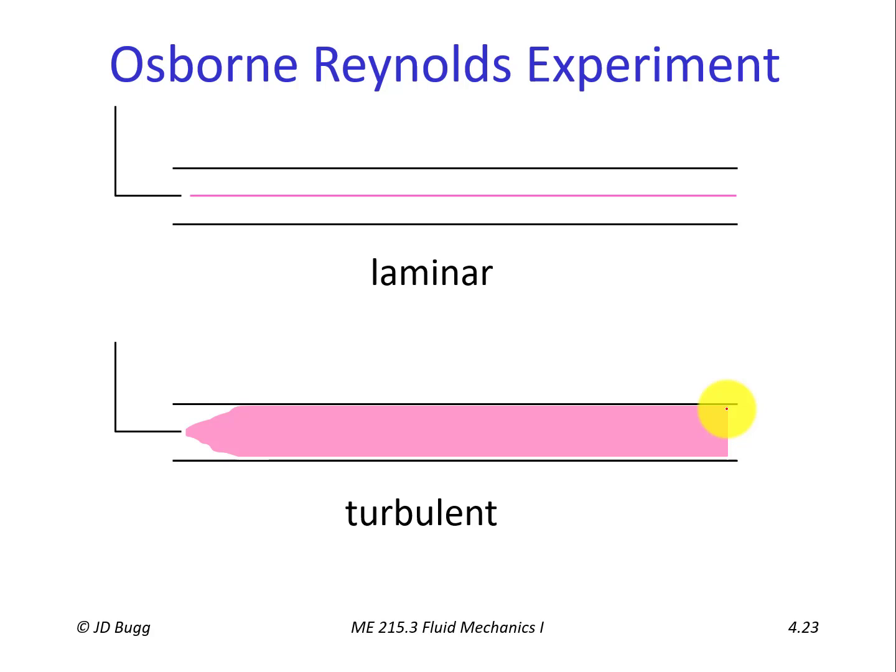So one of the fundamental things that we need to understand as we analyze pipe flows is the difference between laminar and turbulent flow. Because it turns out that the way we calculate that friction factor is different for laminar and turbulent flow. Eventually we'll see the equations that we use, but there's a different equation for laminar and turbulent flow. Now, before we worry about the equations to calculate friction factor, we need to continue this discussion and understand what Reynolds number is, because it's used to calculate that friction factor.